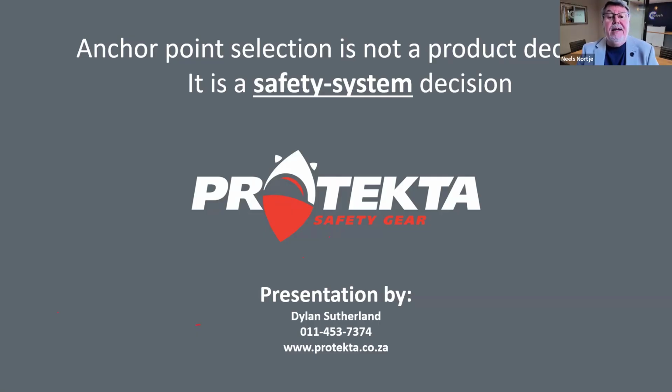Tumelo asks, hi, can a crane be used as an anchor point when offloading equipment from a truck, for example, a compressor? Ideally not. Like I just said now, you can have an engineered anchor point, a self-identified anchor point, or a certified. That could be considered a self-identified anchor point because, if you think about it, what I mentioned earlier, it can hold a 1.5 ton bakkie. The problem though is there are other components to that equipment, meaning if somebody accidentally hits a button and it pulls the person up, you're in deep trouble. So ideally, no, don't cross the two.